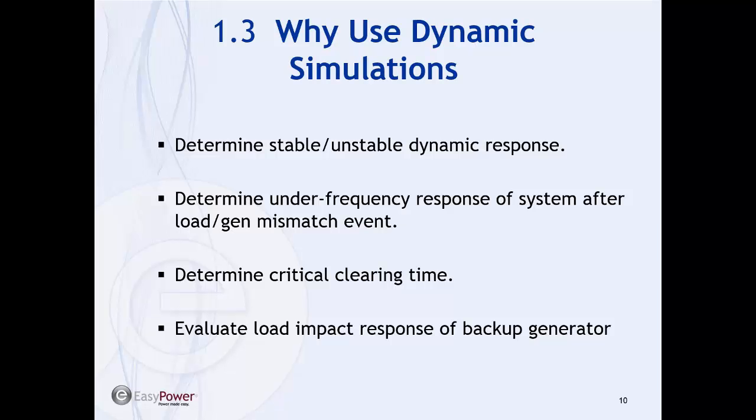And if you look at it in a broader way, you would notice that there are a lot of calculations that we perform every day, and we simply overlook the fact that we are just going from point A, which is the start, to point B, which is the settling point of the system. We are not looking at what happens in between. I go back to that load flow short circuit example that I gave earlier in the presentation. During the time that, let's say, a motor starts or a breaker closes or opens, there might be over voltage, there might be under voltage, there might be frequency changes that affect your system.